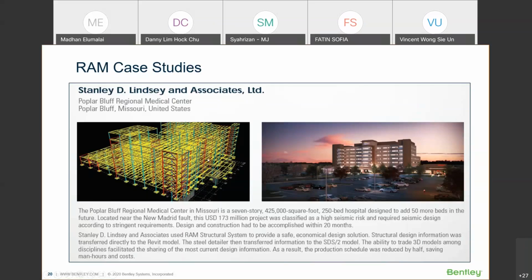The red color members are lateral members, so they need to have a moment connection. Okay, so the expensive moment connections are a little bit time consuming on the site. So instead of having many members taking lateral load and many connections designed for moment connections, we can have fewer lateral frames on each side of the building, and more of the members just participate in gravity loads.